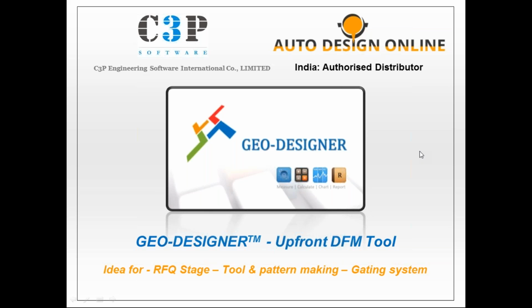So the purpose of this webinar is to understand in what minimum possible time, whether it's at the RFQ stage, at the gating system design stage, or any other, the user can find out very much information about the casting part, about its mass distribution, the location where hotspot or shrinkage could arise, where they should put a riser, where a high exothermic sleeve could be required, and so on and so forth.